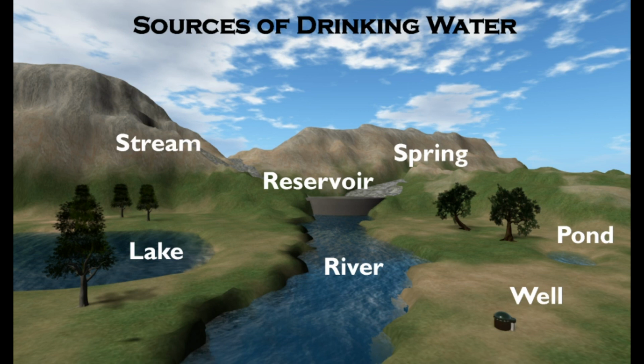A little contamination of groundwater occurs from organic and inorganic soil particles, animal and plant debris, fertilizers, pesticides, microorganisms, etc. as it flows through the soil layers. In spite of this contamination, infiltration causes partial removal of suspended particles including microorganisms. Organic substances are also degraded by oxidation. Partial removal of microorganisms occurs by the death of cells due to lack of nutrients.